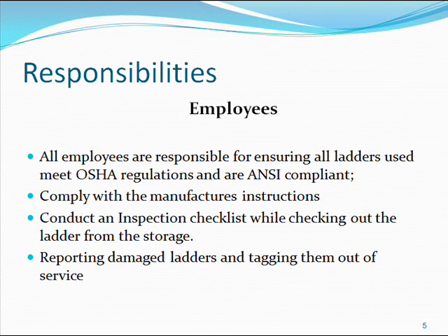Employees' responsibilities. All employees are responsible for ensuring that all ladders used meet OSHA regulations and are ANSI compliant. Comply with the manufacturer's instructions. Conduct an inspection checklist while checking out the ladder from the storage. Report damaged ladders and tag them out of service.